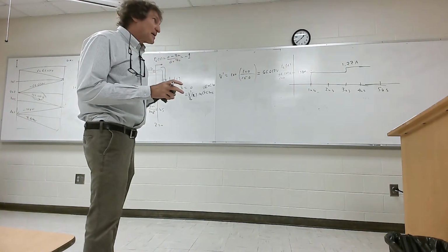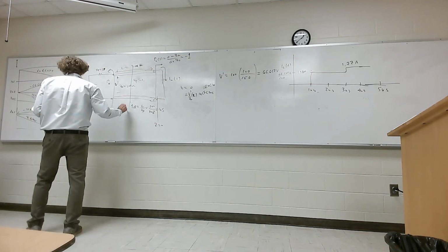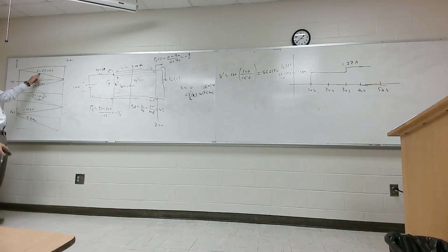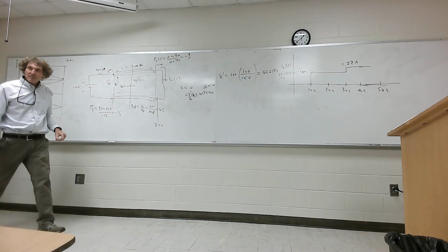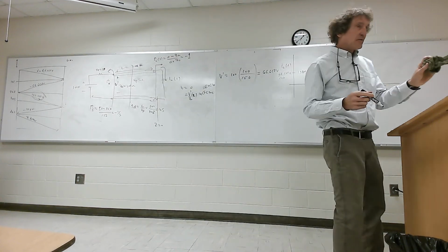Now, if we were talking about the voltage anywhere, like in the middle of the line, we just do it the normal way. Come here, go straight down, at TD over 2 or at a half a microsecond, we go to 66.667 down here, goes to 0 at that point, stays 0 until here, then 22.223, goes to 0 and so forth. So you all follow me? That's how you do that problem.